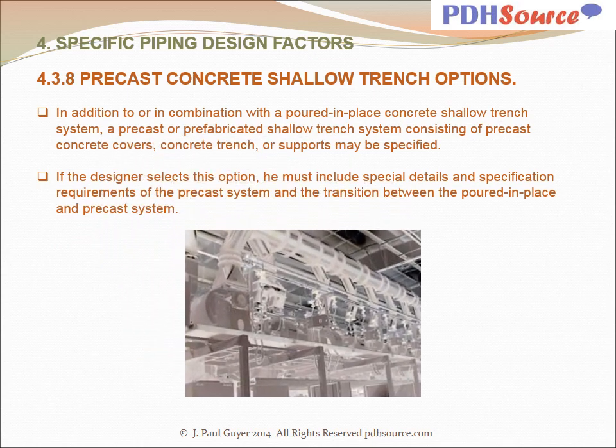In addition to or in combination with a poured-in-place concrete shallow trench system, a precast or prefabricated shallow trench system consisting of precast concrete covers, concrete trench, or supports may be specified. If the designer selects this option, he must include special details and specification requirements of the precast system and the transition between the poured-in-place and precast systems.